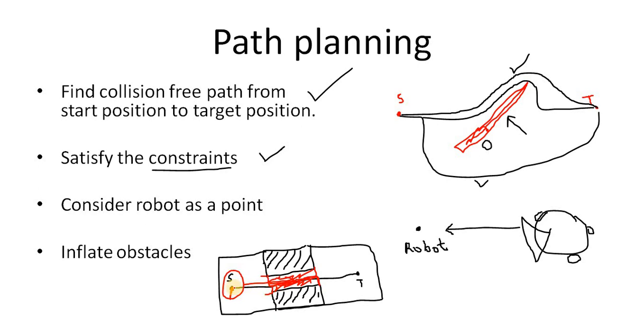and now when I move this point from here to here, there is no space, so it means there is no path here. A path doesn't exist. But when we do motion planning, we have to consider the geometry of the robot, how it looks, what its dynamics are, how much friction there is, what the angle limitations are, how much force it can generate, and what the limitations on the force are. All these parameters we have to consider in motion planning.